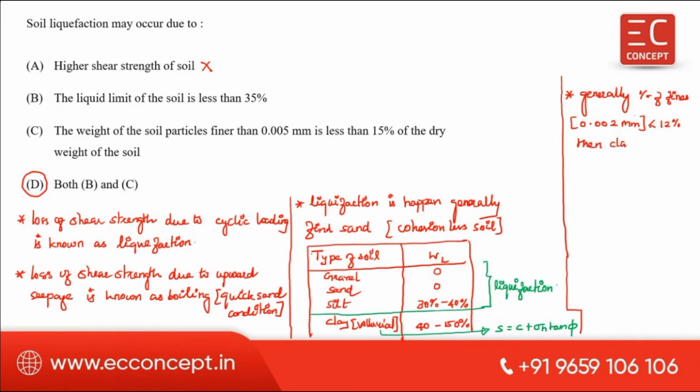classification of soil is done mainly by CU and CC. What is CU and CC? CU is the coefficient of uniformity. CC is the coefficient of curvature. These two only hold good for coarse grain soil.